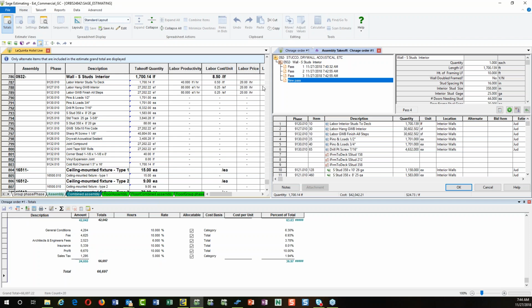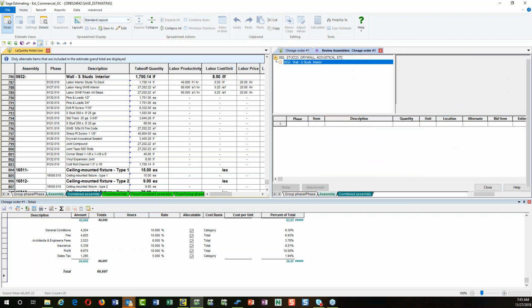If it's a change order that isn't something that changed, but something that they've added, like added a wall or something like that, we can do that also, where I can go over and add a wall, call it my change order, and take care of it that way, and it'll be an added item on here that we can label as change order. Then sort our estimate by change orders, and those that are not changed will be all grouped, and those change orders that are separate will show each one individually. We can do the same thing with alternates too, so that's one way. Hopefully that explains it.